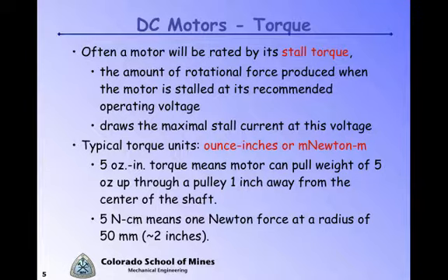You'll look on some data sheets, and we'll look at one in a little while, and you'll see that. Basically that is the maximum amount of torque that this particular motor can produce, and correspondingly it also implies the maximum amount of current that this particular motor can handle. It's not a good idea generally to stall motors and leave them in that condition, because they will tend to overheat and in many cases will fail.